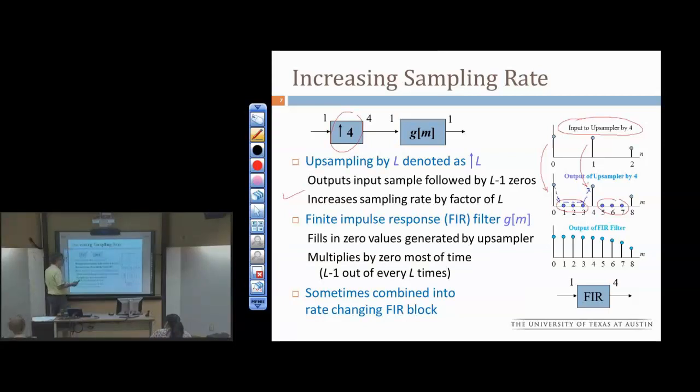For example, we looked at this in communication systems. This was the symbol rate, and then we had 4 samples per symbol. And then this became the sampling rate for the communications transmitter. So it's a fixed parameter. But it is essentially kind of like a compatibility layer, to make it so 2 devices, or 2 subsystems is probably a better way to think about it, in the same system operating at 2 different data rates, and those data rates are related by a rational factor. And so this is an integer factor.